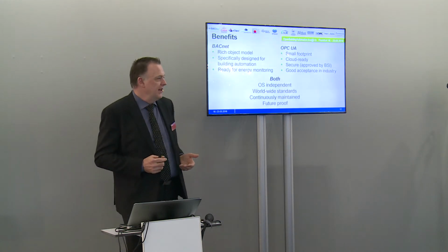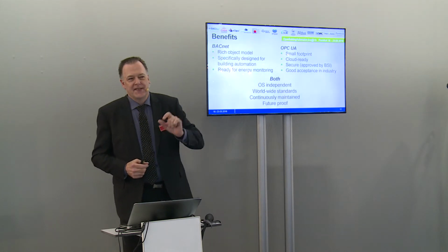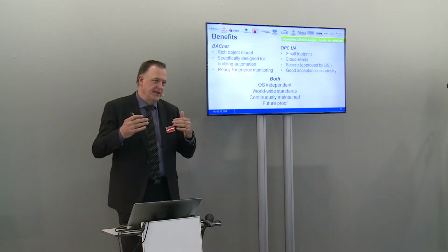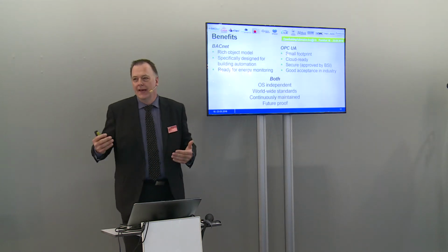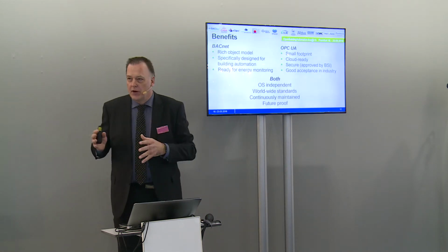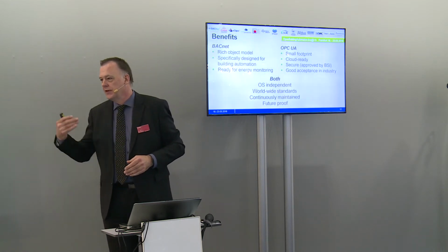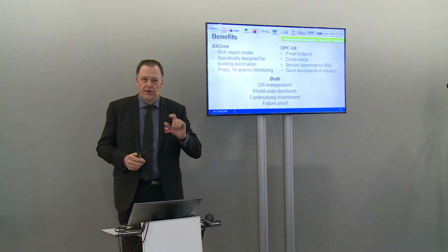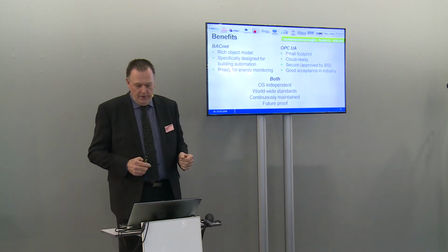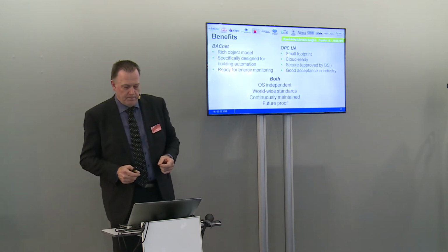OPC UA comes from the industry side. OPC UA has a small footprint. Some of you may even know the old OPC DCOM based. That was based on a Windows operating system. You always were required to run on a Windows system. With OPC Unified Architecture, this is not necessary anymore. So in this case, you can run OPC UA with a very, very small footprint. There are even devices on the market which have a 10 to 15K footprint as a small RFID reader.